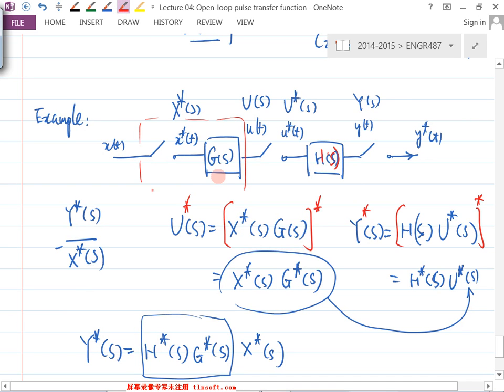This block and then this block, right? The commonality, basically they are separated by what? By these impulse samplers here. So essentially, whenever you have a certain H of z, T of z, S of z, Y of z, whatever, you should imagine there's an impulse sampler within that block. So whenever they're separated by an impulse sampler, there are two z functions, and you can multiply them together.